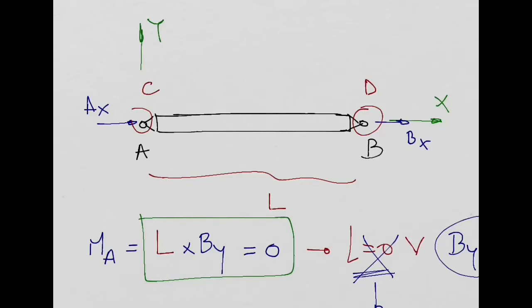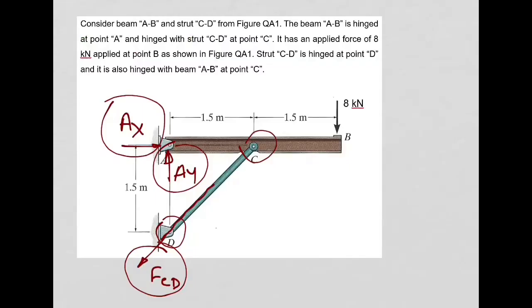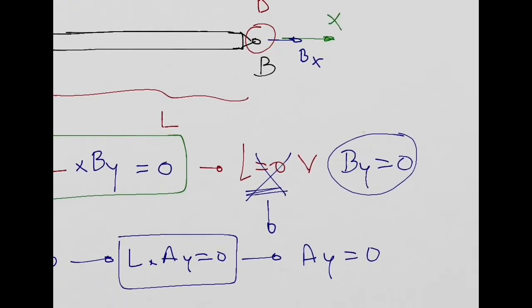When you have a hinge, you have these two reactions, but we concluded here that the reactions in the perpendicular direction to the strut need to be zero, right? So that's exactly what I'm doing here. I'm saying here that this reaction in the perpendicular direction of the strut cannot exist. Because of this here. I show it here, right?